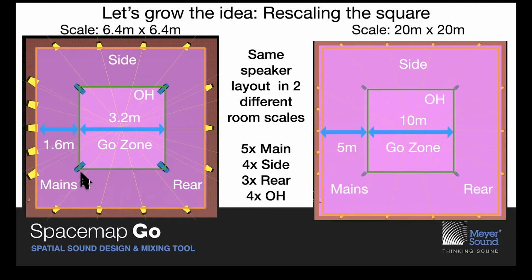We use the G factor, the go zone distance, to set lateral speaker spacing. So you can see this distance here is the same as that spacing there. These are also at a height of 1 G, somewhere between 1/2 and 1G is the height. At anything less than 1/2, you're going to not be able to get any kind of depth of coverage into the room.